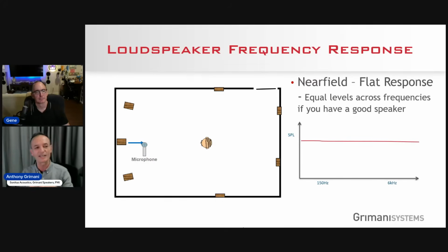It doesn't sound good. Well, in audio, when you look at what's called frequency response, which is frequency on this axis and either voltage or sound pressure level on the other axis, when you're putting in a test signal that's equal level into the system at varying frequency, you want to get back the same thing, equal output at all frequency. And when the result is a flat line, that's called a flat response. In medicine, flat line, not good. In audio, flat line, good.